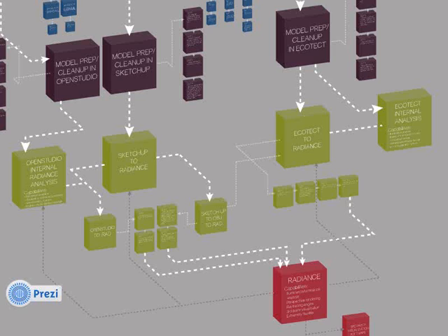So, SketchUp to Radiance: there's a way to take those files. You have to get them from SketchUp to an OBJ format, to the RAD format, which is the .rad file format that Radiance needs. So there's a whole slew of things you have to do to prep it. We won't get into that too much, but we did want to show those actual pathways. Also, you can see that OpenStudio has a line connecting to an OpenStudio to RAD as well. So you have a certain amount of capabilities directly within OpenStudio on an easy level, but there's a way to prep that and get it into just hardcore Radiance on the back end as well.